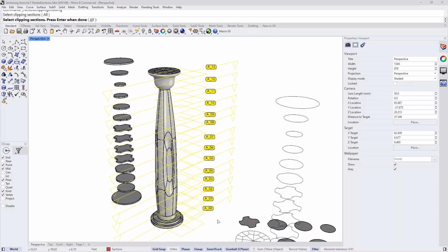If you take a slice of your solid object, you get an upper outline and a lower outline, and then you need to project those onto a common plane and capture the perimeter of those two outlines, the maximal perimeter of those two outlines, and that becomes the outline that you drive your laser.